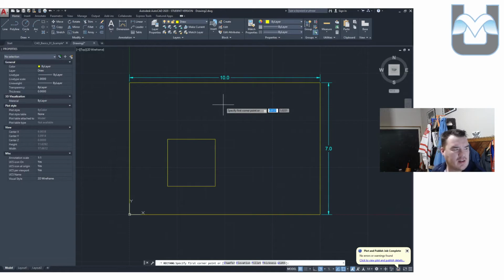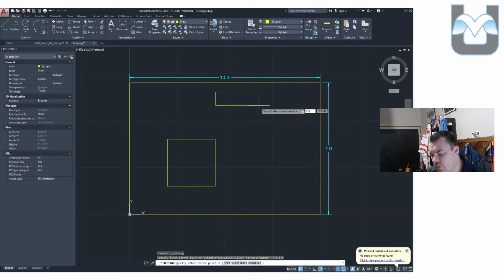Okay, I've got a couple of the shapes that we're going to throw in here. We're going to throw a rectangle at the top. It is 4.5, 6.5 to start, and it's kind of funny because this one goes to the right and down, which means that when I give this width and height, I can give it the normal width because we're going to the right, but for the height I actually have to give it a negative number. The negative number is going to drive this downwards. There we go, -1.